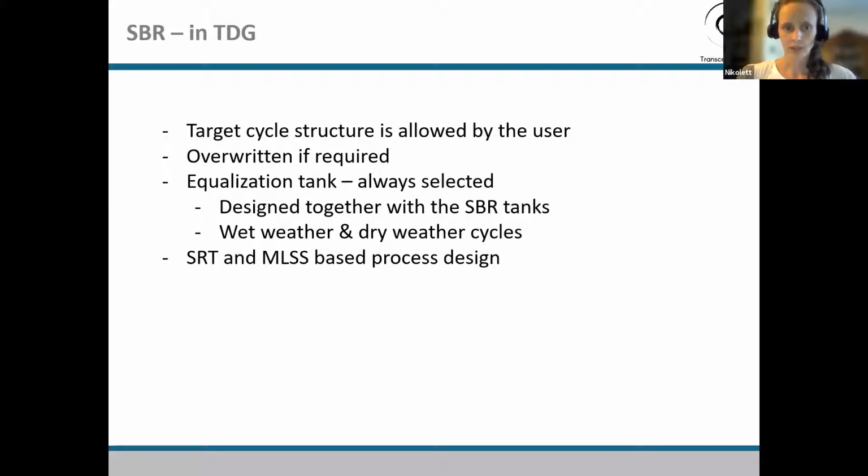Also regarding the equalization tank, it is always selected and it is designed together with the SBR tanks. In the next slide, I will show what I mean by designed together with the SBR tanks. And all of the calculations are done for the wet weather and for the dry weather cycles if the wet weather flow conditions are given by the user.